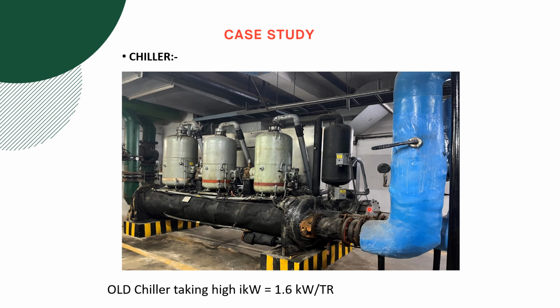So I'll give you the details of this, and before going to that, let me give you a brief of what a chiller is. So chiller is the main component or a main part of HVAC, heating, ventilation, air conditioning system in a building, or we can say it is a main component of a centralized AC system. It is a water cooled chiller. So water comes in from here and goes out from this pipe,